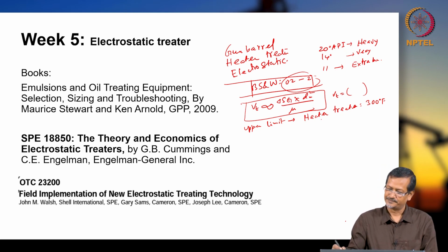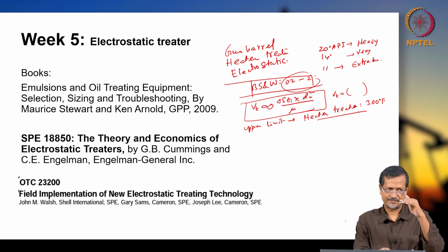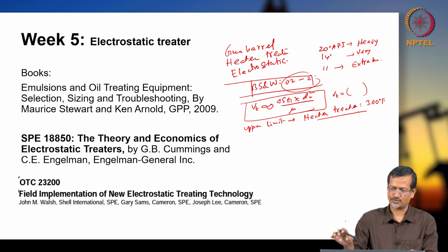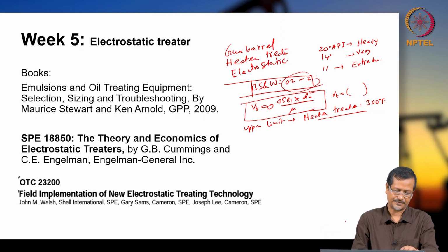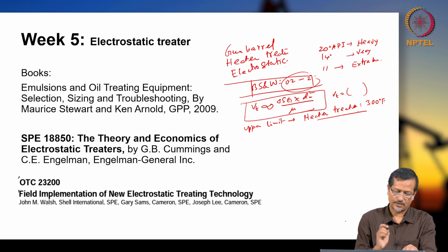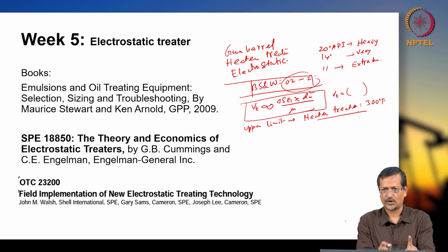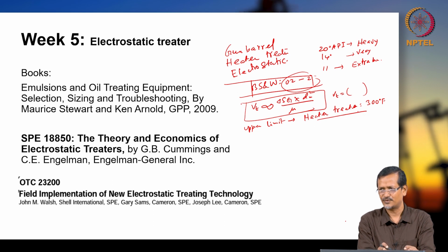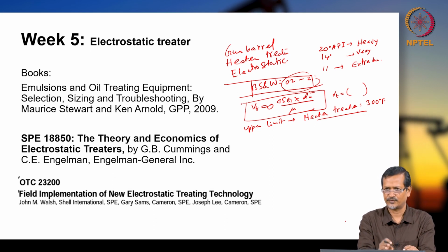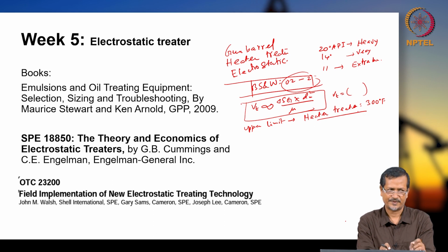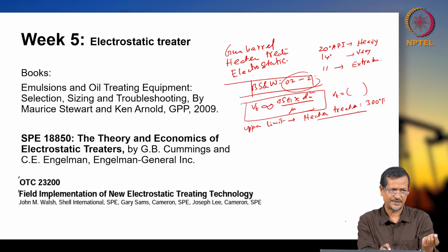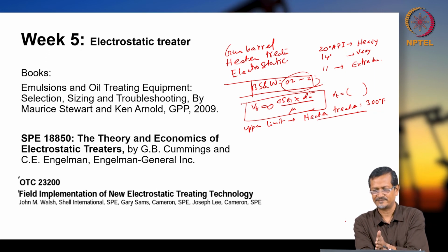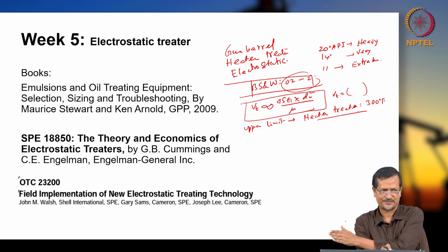So, you should give that limitation of temperature, and for safety and other aspects also you will be controlling this maximum temperature. Normally in an oil field, crude oil will be producing a certain amount of water every time. Without water, getting oil from the wellbore is a very difficult job. Some amount of water, some amount of debris, sand and other particles will be there. That is why you need all these mechanisms like the heater and electrostatic heater.